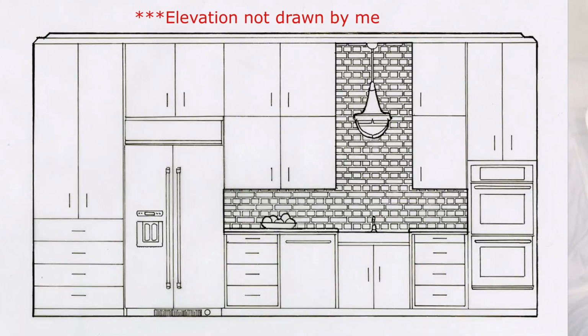So on a floor plan, I can figure out how wide a doorway is, but I don't know how tall it is if I'm not looking at it through an elevation or straight on. Or, for example, in a kitchen, I wouldn't know if the kitchen cabinets open this way or the other way without an elevation. An elevation will also identify those things for you, the direction that things open. If you have cabinets that are really tall and go all the way up to the ceiling, I wouldn't know that if I wasn't staring at a flat elevation. From a floor plan, I can't tell that.